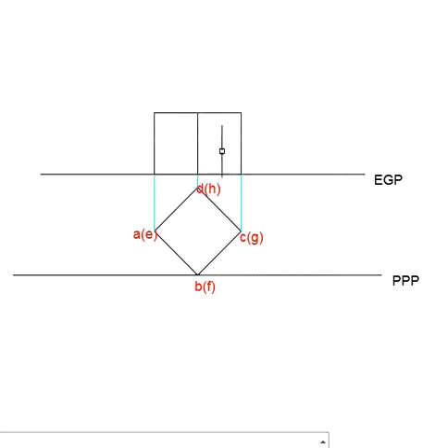You can see the center line, and you have to mark all the 8 points in the front view also. So this is the front view of the object. We marked all the 8 points. Now you can mark the dimension lines. Just mark the dimensions. It is 25. Here also it is 25.